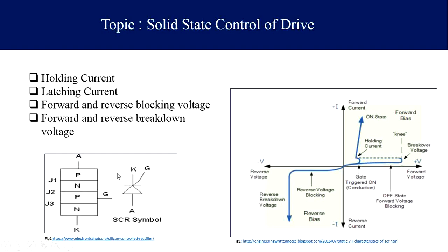Since we have given negative voltage to the anode point, this voltage will go on increasing and increasing. After a certain limit, it will make the SCR go into breakdown, that is, it will suddenly make the reverse current start to flow. This point is called avalanche breakdown, when very high reverse current will start to flow from that